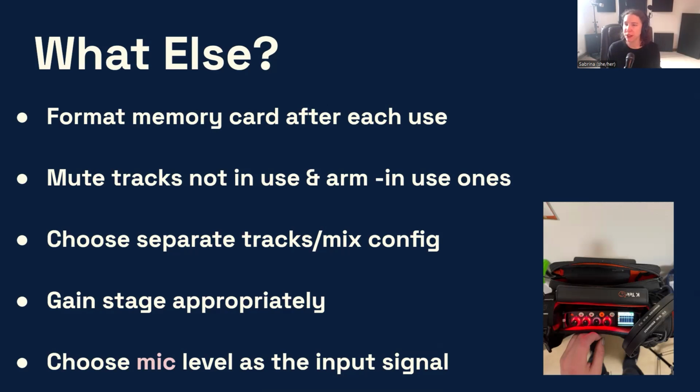Some other best practices are formatting your memory card after each use, muting tracks that are not in use, since that can also introduce noise into our signal, choosing separate tracks in mix configuration, which means if you have the ability to say mix only for all the tracks or separate tracks, make sure you separate tracks, gain staging appropriately, and choosing mic level as the input signal, since that's the highest quality signal.